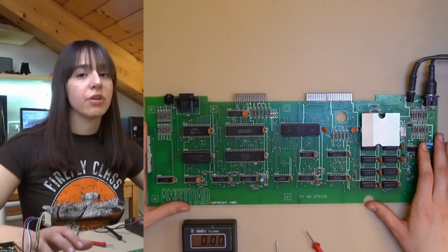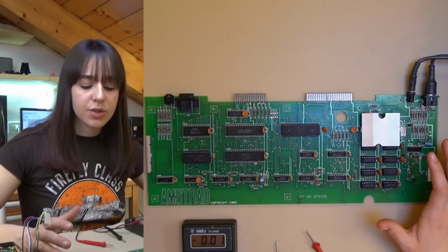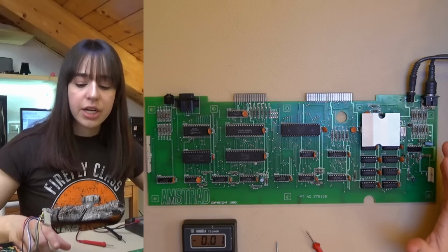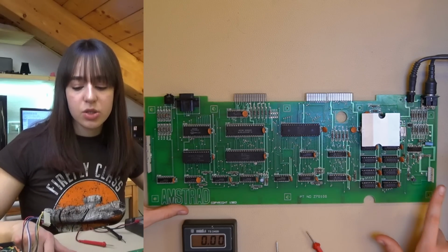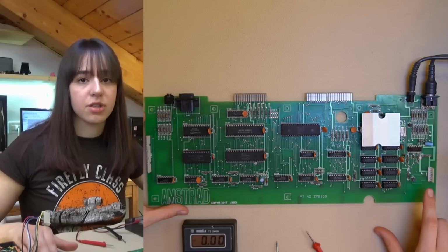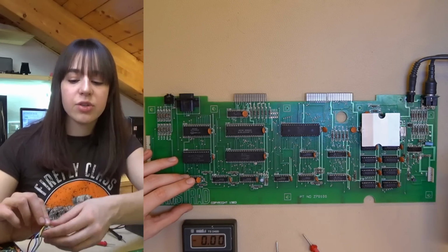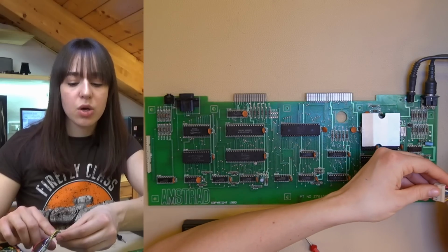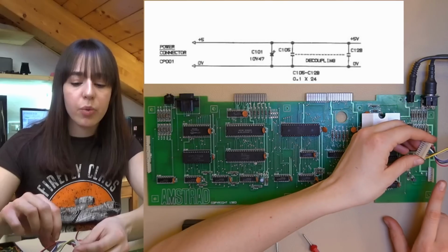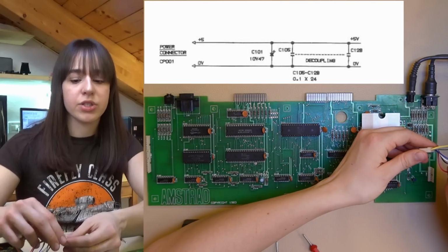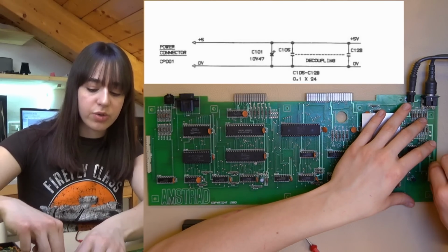At this point, I'll focus on the board and I'll check the voltage, but in this way the board will never work, because the computer has a switch that is connected to this, so unless I close that circuit, the board will never work. And it's quite inconvenient to connect it in this way, so some people use the same connector that will go here, but with the red and white wires connected together. In this way, the circuit is closed.